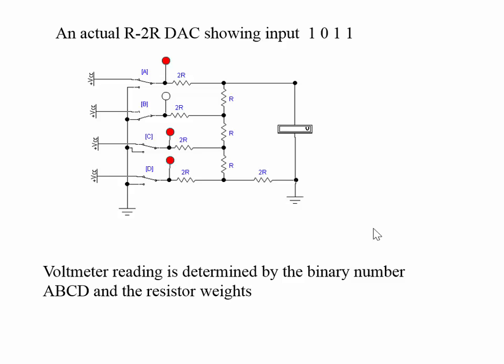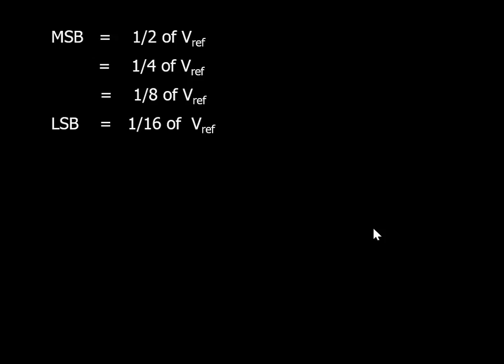So all this is saying is if we were to look at this particular circuit and analyze it, it would give us the results we would expect for a 4-bit digital to analog converter. Because if V reference is equal to 5 volts, this value here is the number 8, so this is 1000. 8 is roughly half of 15, so that would represent roughly 2.5 volts.